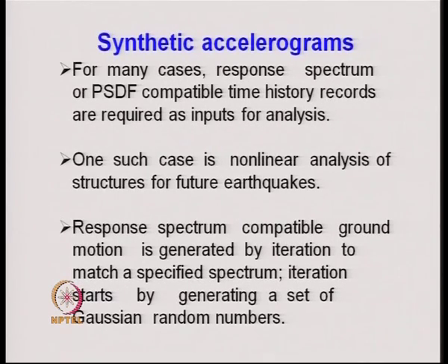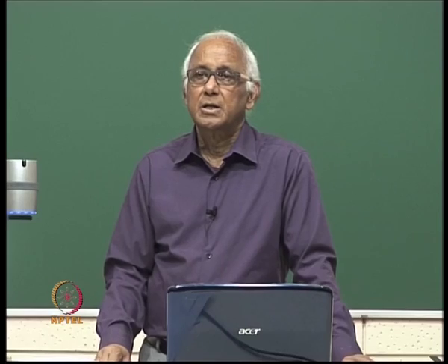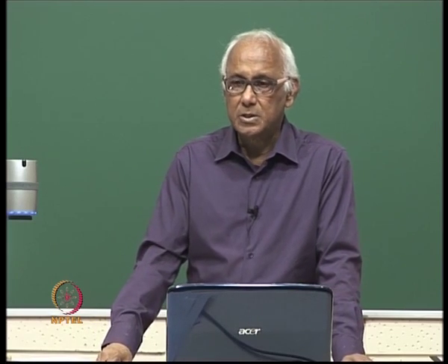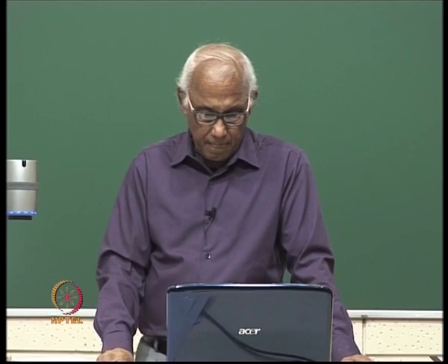So, these time history records which are generated from the given response spectrum or given power spectral density function, if they are used for constructing back the response spectrum or power spectral density function, they will be the same as the ones from which they were generated.